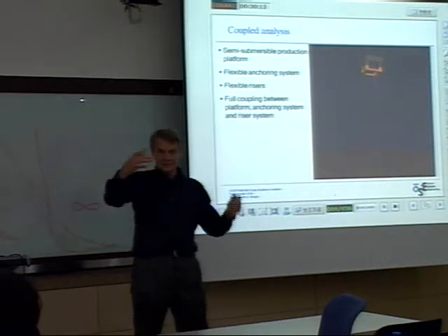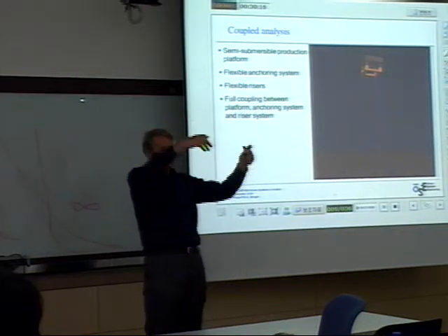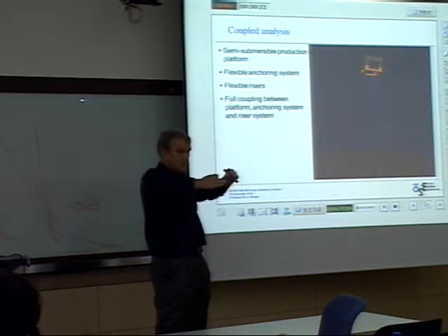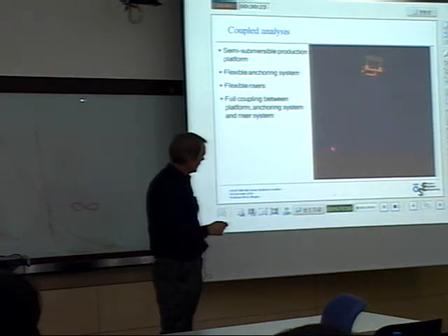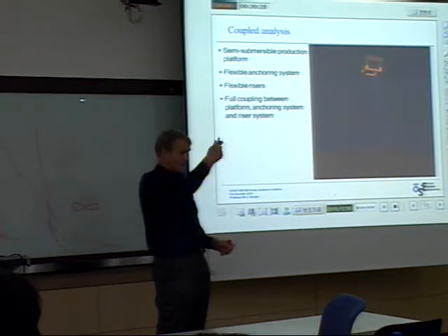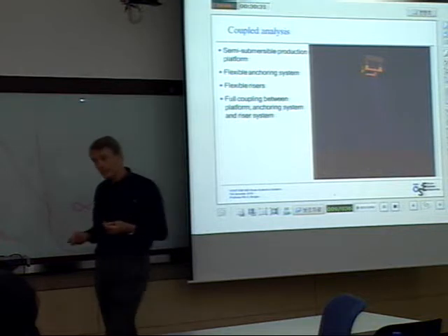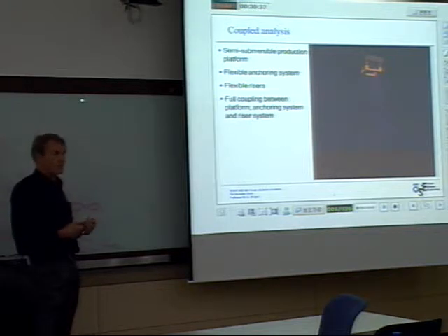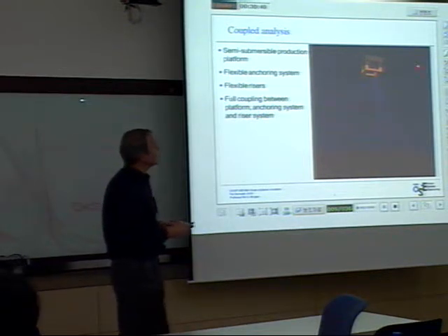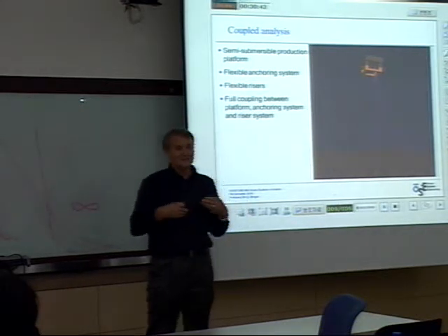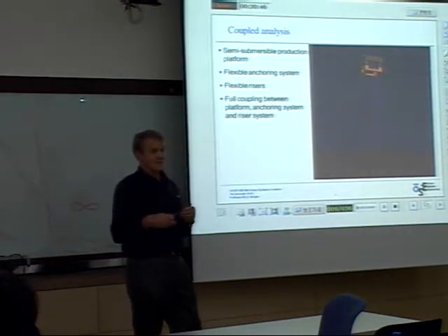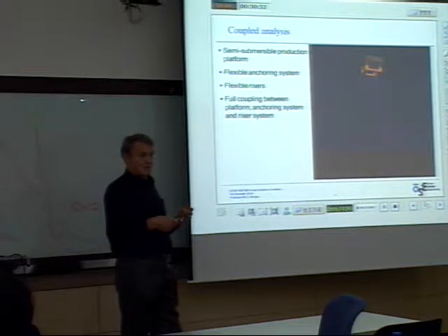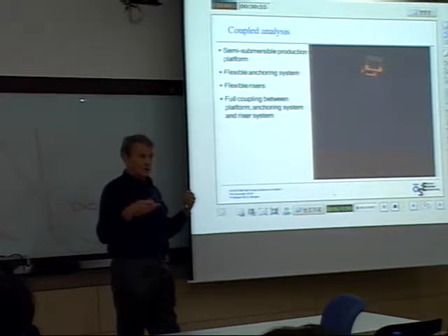In this dynamics simulation, you see the platform moving up and down and rolling, and you see the anchoring line being stretched and pulled, and these risers also go up and down. Today, with nonlinear finite element formulations, you can do this kind of simulation, but it is quite complex, depending also on how much fluid dynamics, CFD, you put into this. Of course, you can do simplifications, but ideally one would like to simulate a